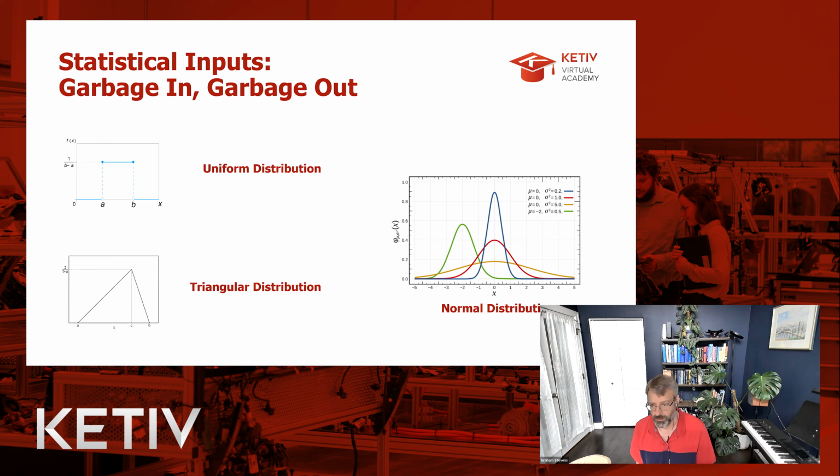So one thing that's really important on a Monte Carlo analysis is those distributions. If I'm assuming a normal distribution, that's an assumption. And the question is, is that correct? Or is it skewed? Like, is my manufacturing variable actually plus or minus 5 thousandths or 5 mils or whatever dimension it is?